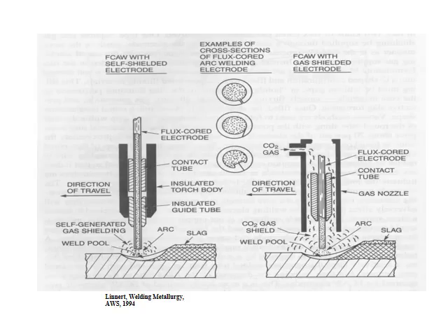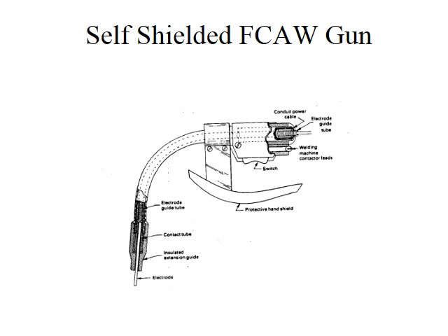Shielded metal arc welding has the same flux, not exactly the same, but the same flux outside of a metal wire. They just glue the flux on the outside. This, you put it on the inside. But with flux-cored arc welding, you get a better deposition rate because you're not always having to change electrodes. You're in a semi-automatic situation where you're feeding the wire, your electrode coming off a spool, so you can pull a trigger and just go like the dickens.